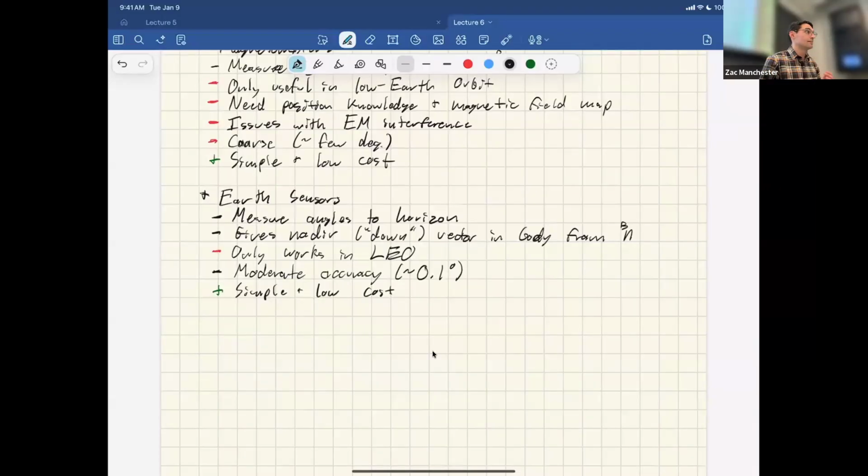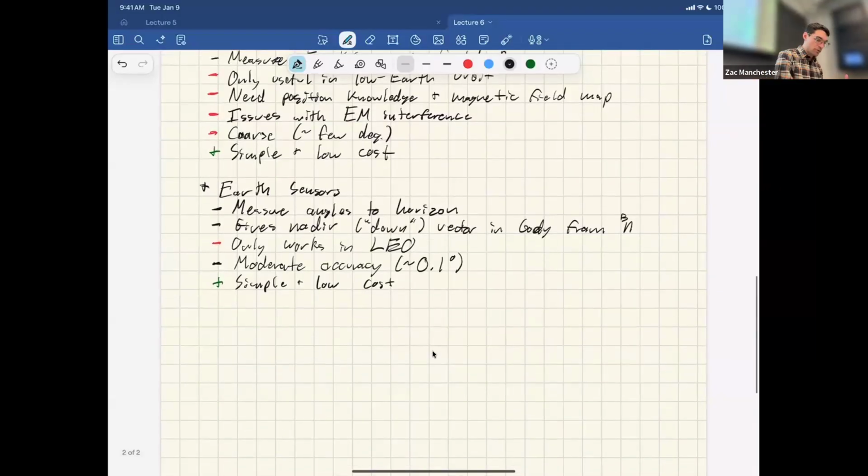So, gyroscopes and accelerometers. Yeah, gyro, yes, absolutely. Accelerometer, not so much. If you're in orbit, you can have a non-zero measurement on an accelerometer because of an omega cross R term if you're spinning and it's off the spin axis somewhere. But otherwise, if you're just hanging out in orbit, accelerometers measure zero, by definition, because you're in free fall. So those are less common. But definitely gyros.